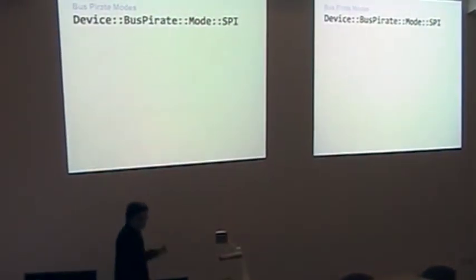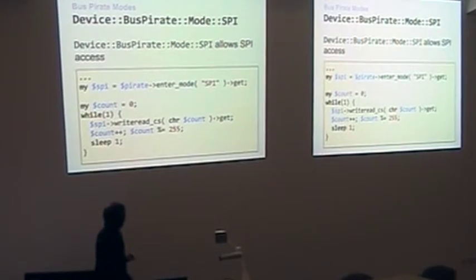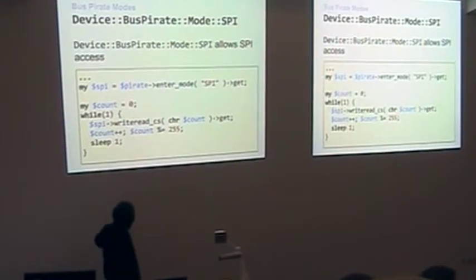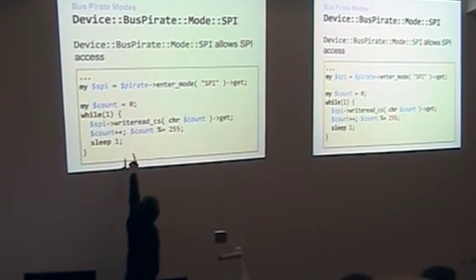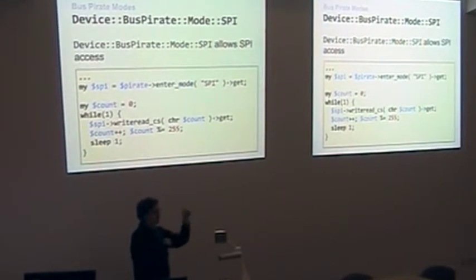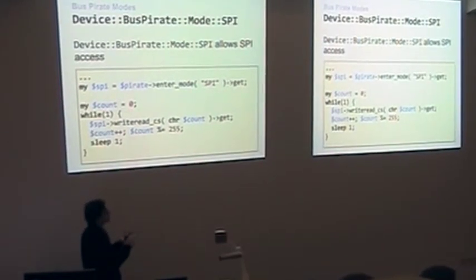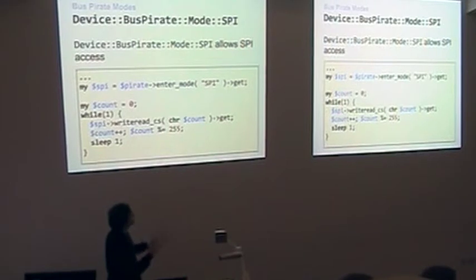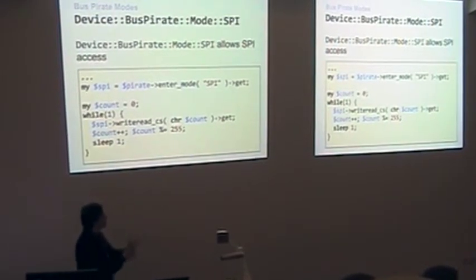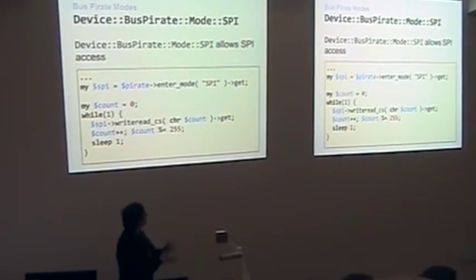So that's that. There's also a little SPI thing, which works in a much similar, exciting way. The SPI object. As I said, with SPI you are simultaneously wiggling the clock line, writing a byte out, and probably reading a byte in. That's all that happens down the SPI wire. So it's kind of up to you to decide, am I expecting to send some data now and probably ignoring what I read, or am I basically just writing zeros and reading something in?